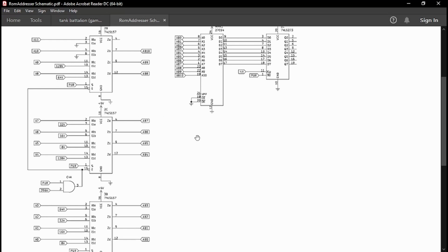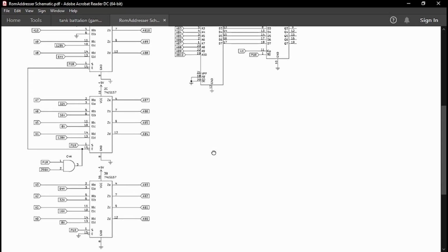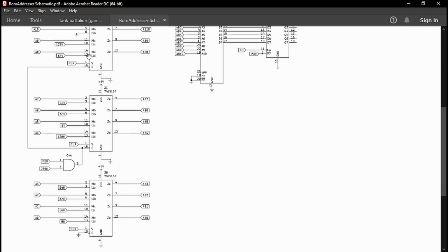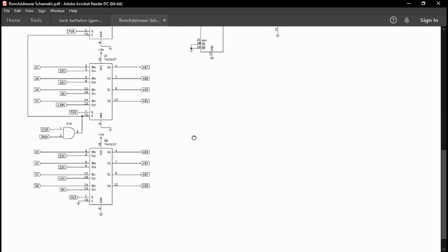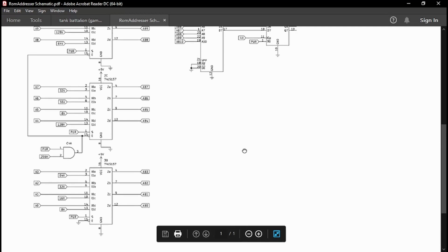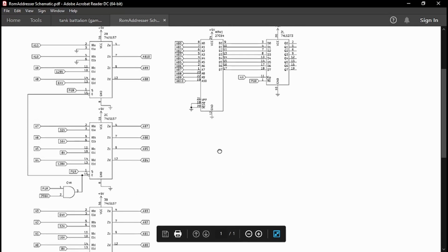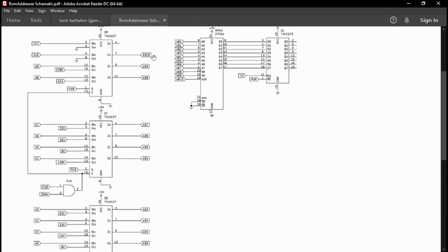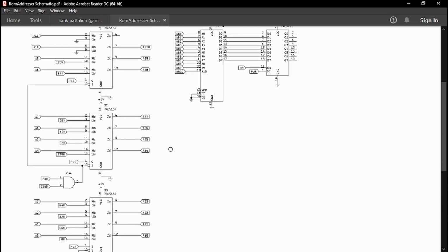And then on the other ones, let's say the second inputs, we're tying the top two to ground, and then we're going to tie, as per the previous schematic, 128, 64, 32, 16 and 8 V, and then the 128, 64, 32, 16 and 8 H. And the outputs are going to go to address bus 10 down to 0.